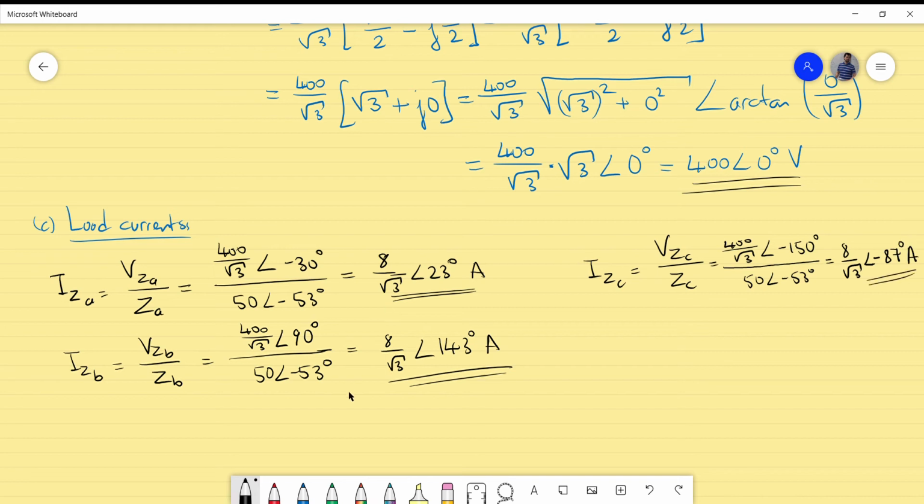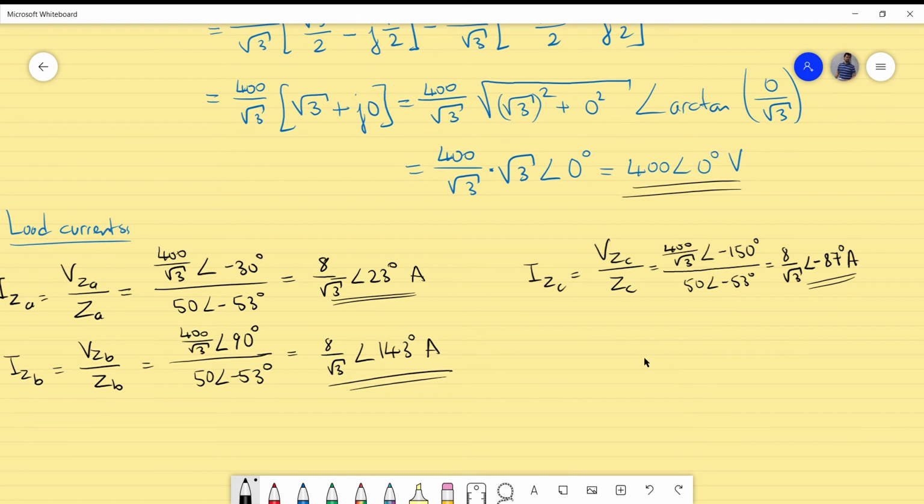I mean 97, excuse me, this one will be 97. So let me correct this. So this will be 97 degrees in amps. Okay, that's actually for the three currents. These are the load currents. So we have the exact same expression for the amplitudes, but the phases will be again plus 120 degrees. This also plus 120 degrees, just addition of 360 degrees, and you will have the expression shown here.